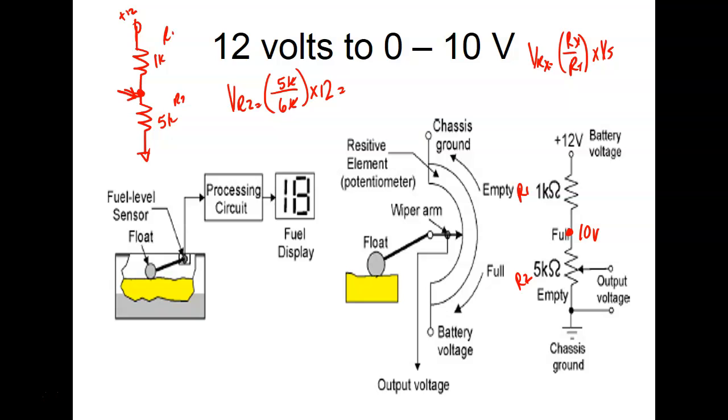So what we've done is we've set the span. I'm powering this up on 12 volts, but I want my span to be 10 to 0. So we're using resistors to set the span. Why did you use 1K and 5K? Because that's the way that it's set up. This could be a 10K and a 50K, or a 100K and a 500K. Any two resistors that give us the same ratio would still give us 10 volts. I did not pick these, Siemens used this. This is off the Siemens test code.